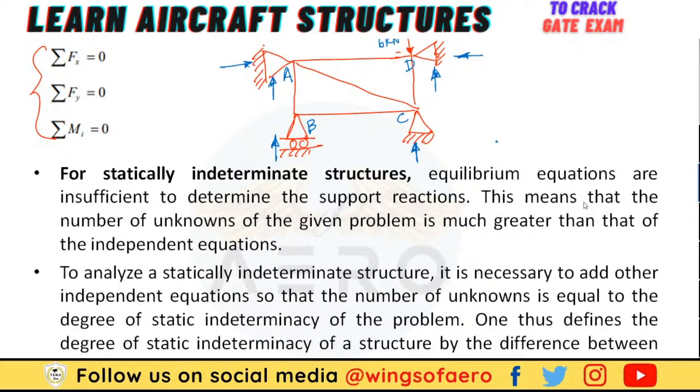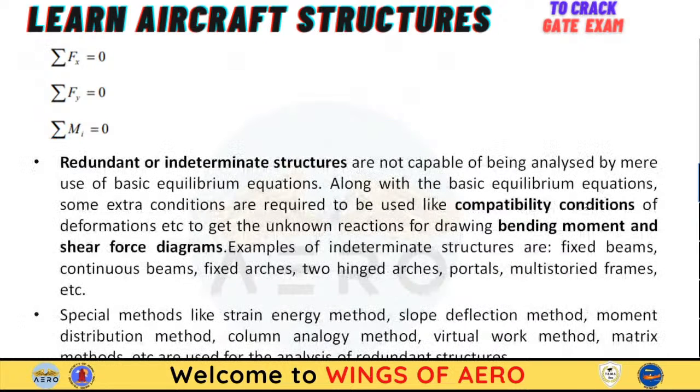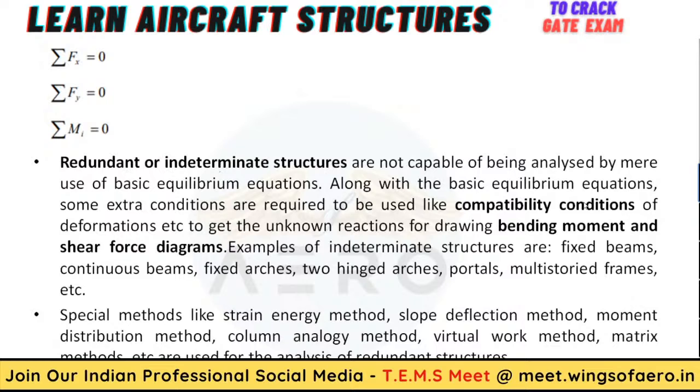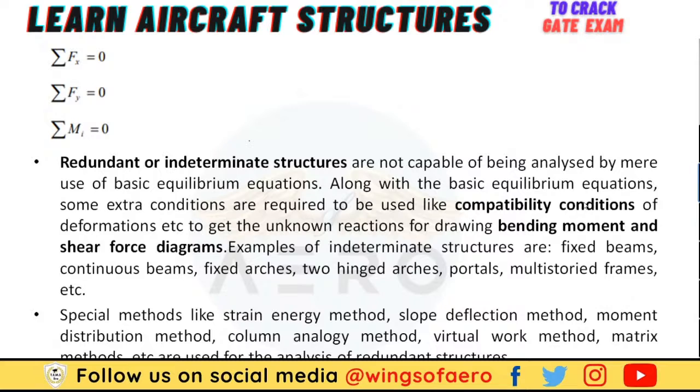There are also many ways to find the degree of static indeterminacy, which we will come to in upcoming slides. This is very important to know: the redundant or indeterminate structures cannot be analyzed by means of the basic equilibrium equations.